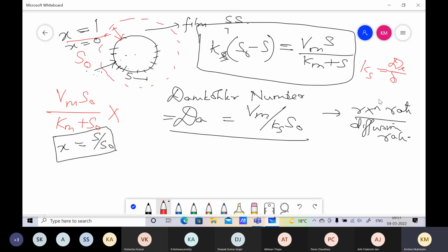Do you remember, diffusivity upon delta, where delta is the film thickness and D is the diffusivity, and delta depends on the rate at which the liquid is flowing. Suppose it's a PFR and this is my flow velocity f, then the flow velocity will determine delta and the diffusivity is fixed, so Ks is determined by f in many ways. Of course, it is not a linear relationship, it changes asymptotically.